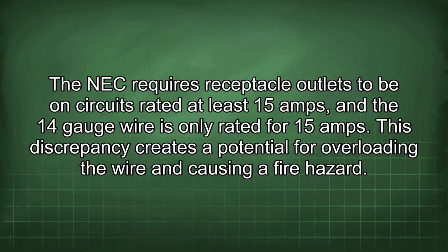The NEC requires receptacle outlets to be on circuits rated at least 15 amps, and the 14 gauge wire is only rated for 15 amps. This discrepancy creates the potential for overloading the wire and causing a fire hazard.